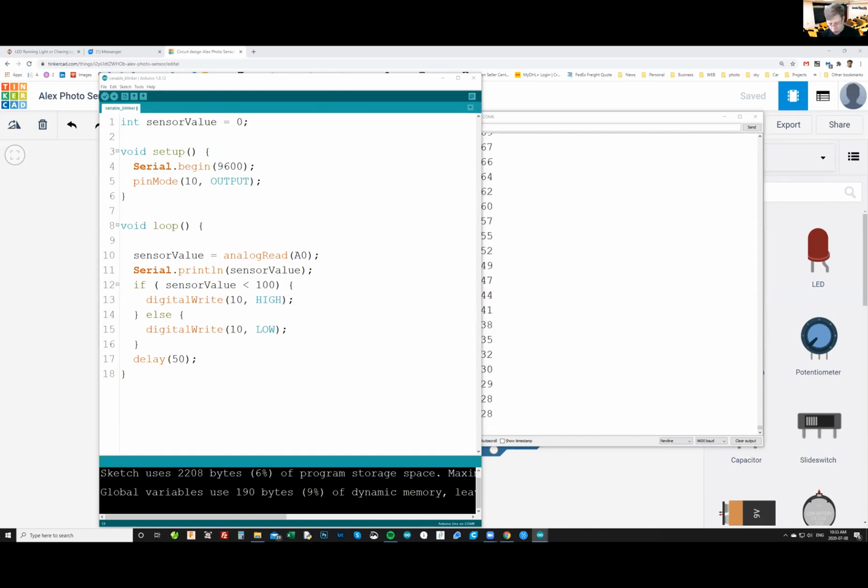So you need to do something with your schematic. It's either the resistor is wrong or you haven't connected it correctly. Maybe the resistors are not the correct resistance? Yeah, that might be it. You need to use a resistor of like 1K or maybe higher, maybe up to 5.